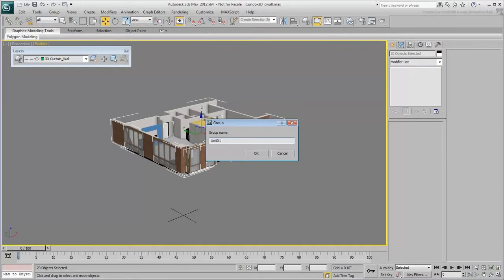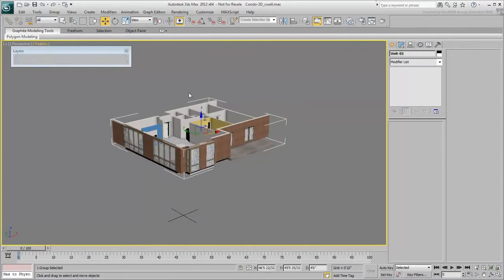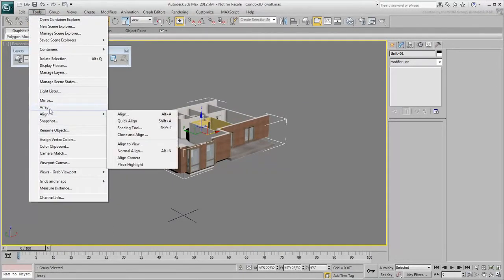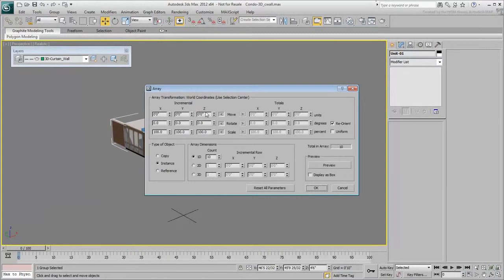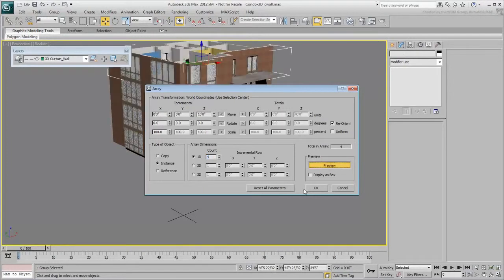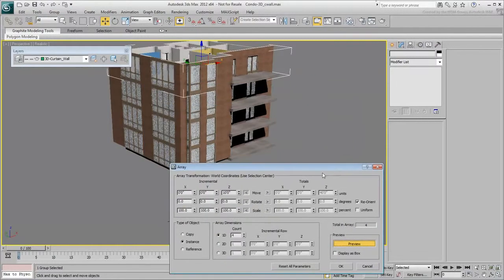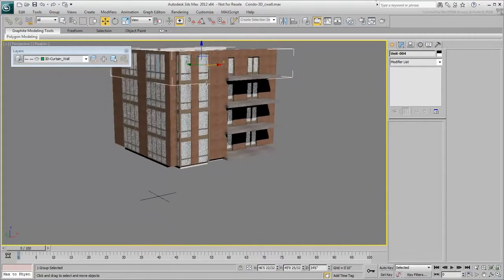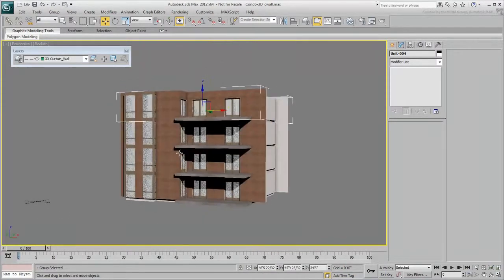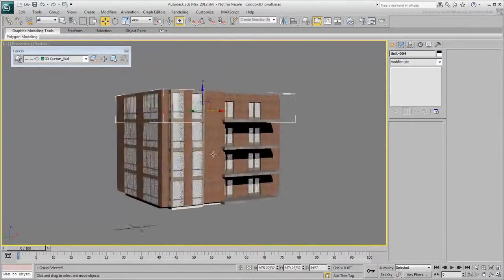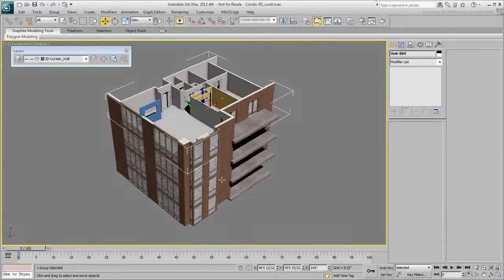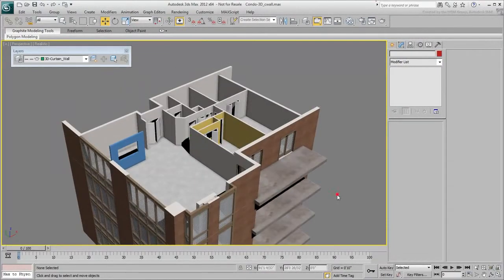Ultimately, you would need to add lighting scenarios, which we are not doing here as it's not the focus of this tutorial. In this tutorial, you have learned to prepare and import a 2D AutoCAD drawing into 3ds Max, and use 3ds Max's modeling tools to quickly build 3D entities. In some cases, you use built-in tools like simple wall extrusions and 3D doors. In other cases, you learn to use polygon modeling techniques to fine-tune the work like bridging gaps and building curtain walls. You have also learned about the importance of multi-sub-object materials and how to manage them.